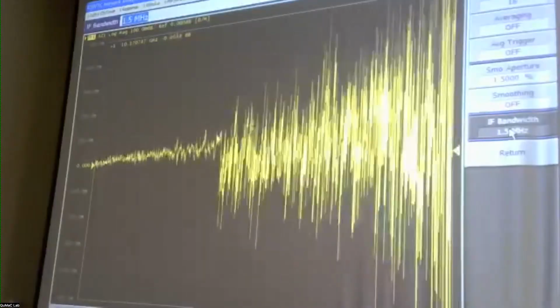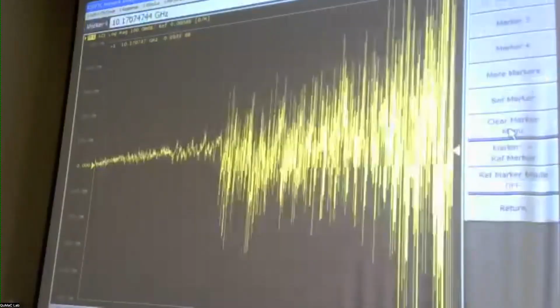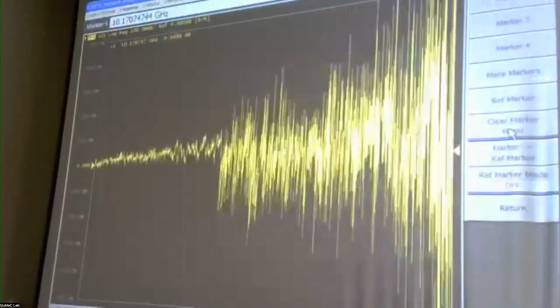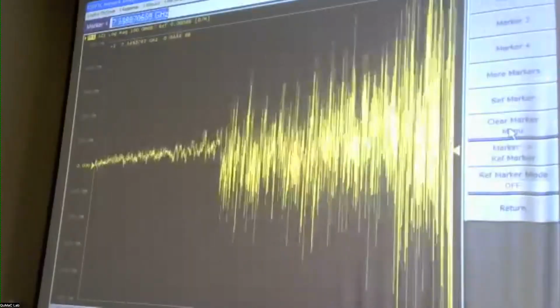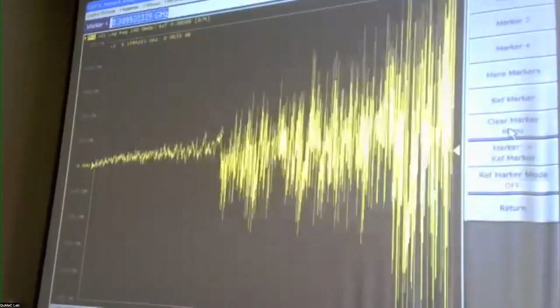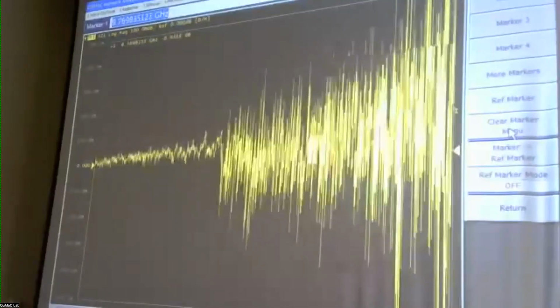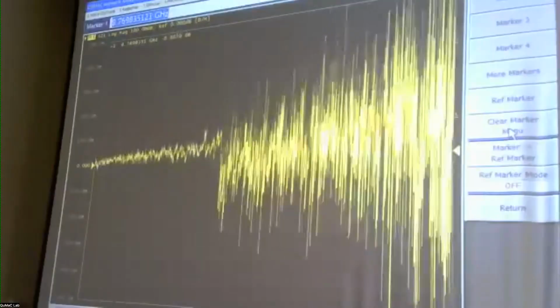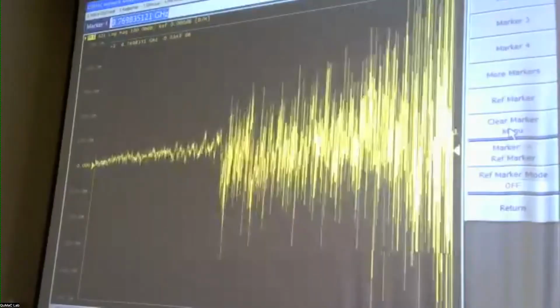So what is that frequency? For this instrument, let's see. There is a menu called marker, which allows you to put a marker here and read off. So roughly it's around 8.5 gigahertz or so. You will see when I go to a lower resolution that something strange happens, that there's a receiver chain which just has an offset.